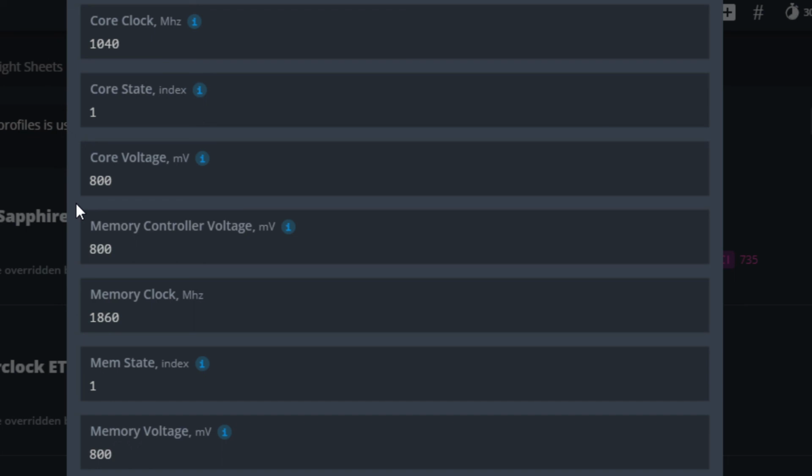In summary, when you are overclocking and setting your clocks for your card, in this particular case the RX 570, but whatever GPU you have, remember it's a process. First, I like to start with core voltage and leave the memory as close to stock as possible. Once we've got our core dialed in somewhat, let's say we're aiming for that 30 megahash again, we do 1110 core at like 850 millivolts, which is plenty of millivolts generally to run stable there. Then we troubleshoot: if it works, lower core voltage. If it doesn't, increase core voltage. Retry.